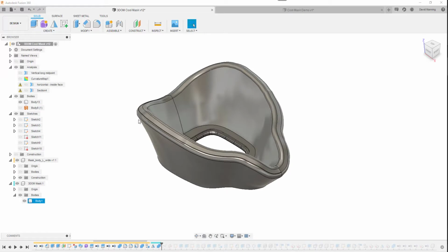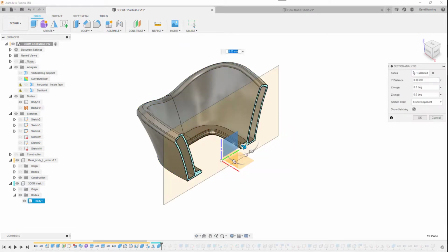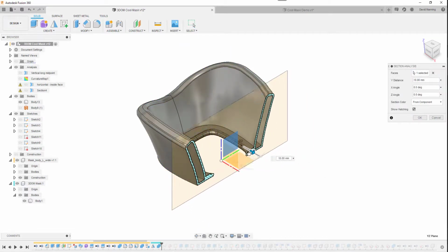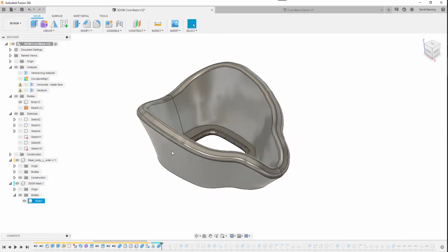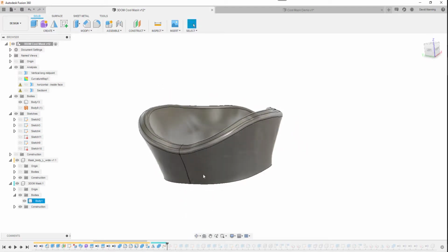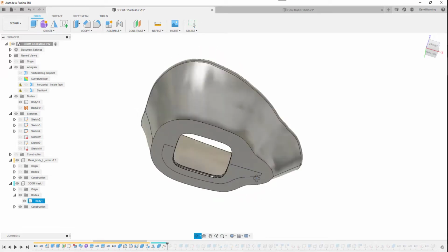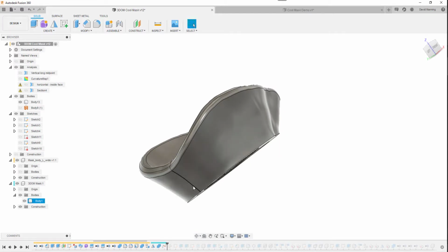Okay, so the next thing is we've got the whole body, single body here, and it is hollow. So if we show you that with an inspection through here, it's a hollow body, and we can print that nicely in hollow. However, we need to get a way to get the fluid in there. So the next thing we're going to do is create some additional resources. What I need to do is put a nozzle on this plane here, sticking out of the bottom of the mask. Choosing that one there because this nose will be up here. That'll be hanging off your chin and be away from your face, and also not obscure anything.